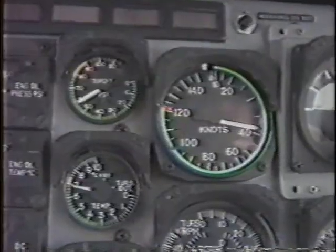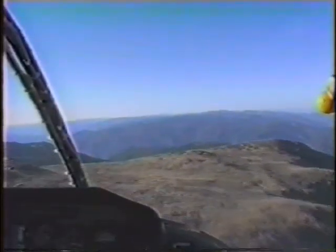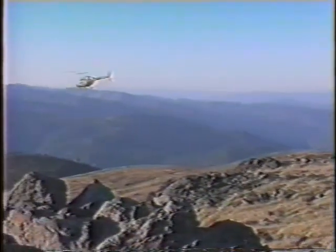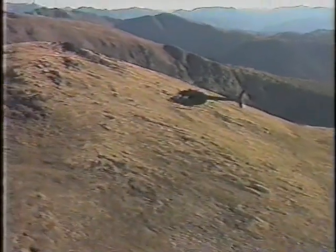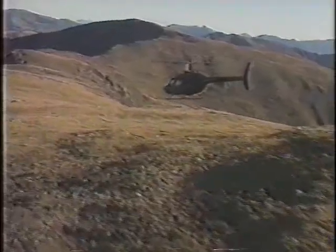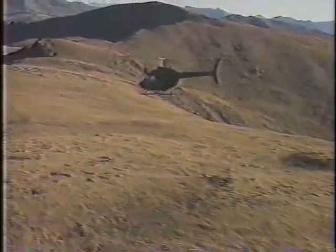It now takes 60 torque to maintain your 40 knots, and your relative ground speed passing the intended LZ is much faster. These differences are telling you something about the wind factors. Do more passes until you're comfortable, constantly repeating your wind-finding checklist: airspeed, altimeter, outside. Time is not wasted doing recces, especially when you're unsure of all the factors in play.